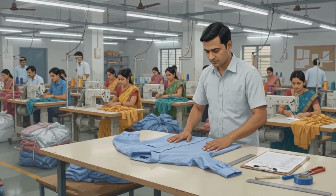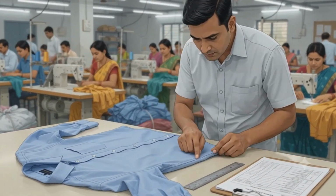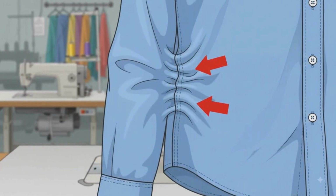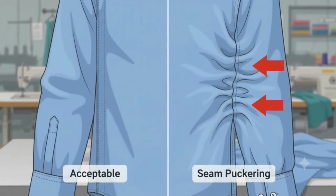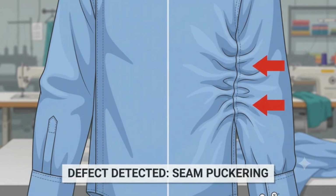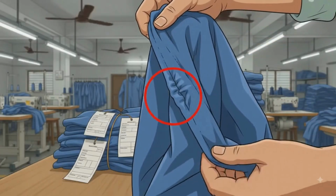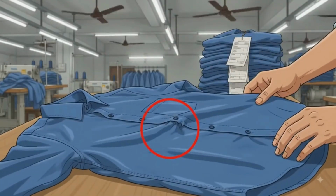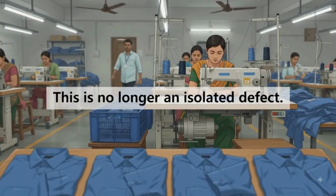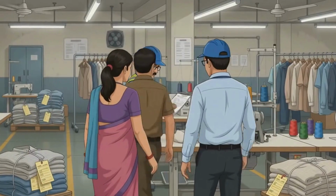During inline inspection, a quality inspector notices that the side seam is not lying flat. Unwanted wrinkles along the stitch line indicate seam puckering, a common appearance-related sewing defect. The same puckering appears repeatedly at the same seam location across several garments. Repeated defects suggest a common underlying cause.